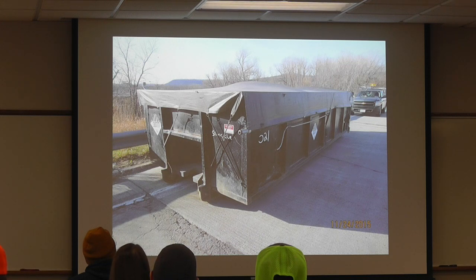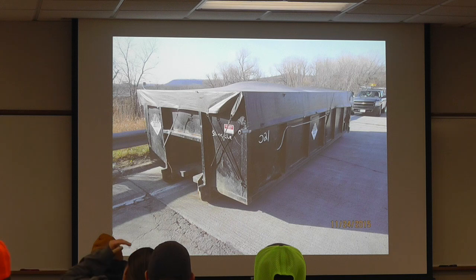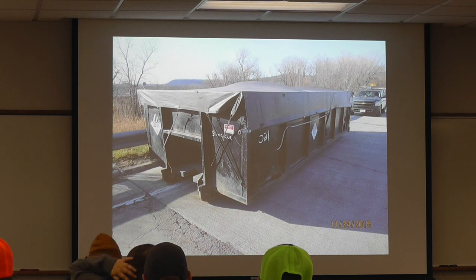For the rarity these days, but it does still happen, they may use a coal slag, like a blast furnace coal slag, as a blast media, blast ox, black diamond, and all of that, every bit of it that comes out of the nozzle gets sucked up and ends up in these roll-offs. You can have just as many roll-offs as you do barrels. So this is one reason we've switched over to using recyclable steel grit, is you don't put near as much material into a landfill, because we fill them up fast enough as it is.